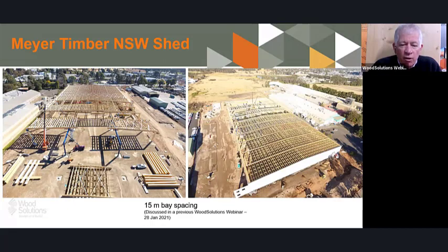So the total volume of wood in the 10-metre spacing is a more efficient design. The I-joists particularly are going to reduce the amount of wood being used considerably, because in reality, it's the purlins and girts which make up the volume of material being used in the building. It's not really the rafters and portal frames, and that's why the changes occur in pricing.